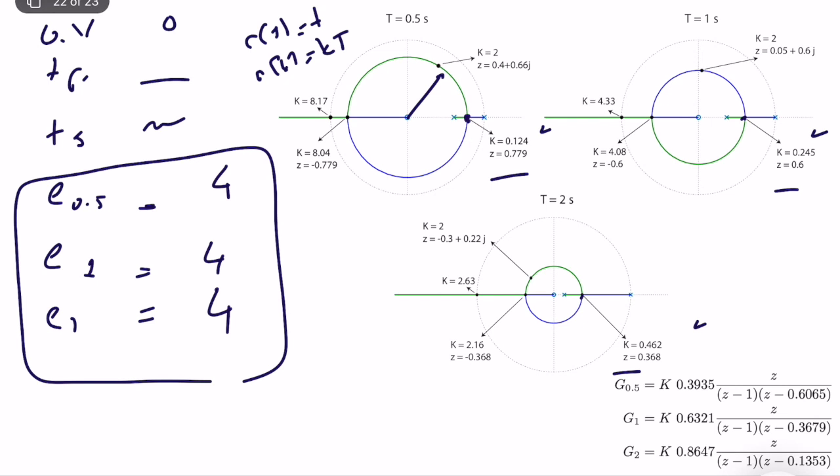But if we limit ourselves to the case where the root-locus is technically critical damped at this location, for this system, when we change the sampling time, almost nothing changes between the performance results. So this means that comparing root-locuses when you change the sampling time is quite complicated. It's more complicated than comparing root-locus plots in continuous time domain.